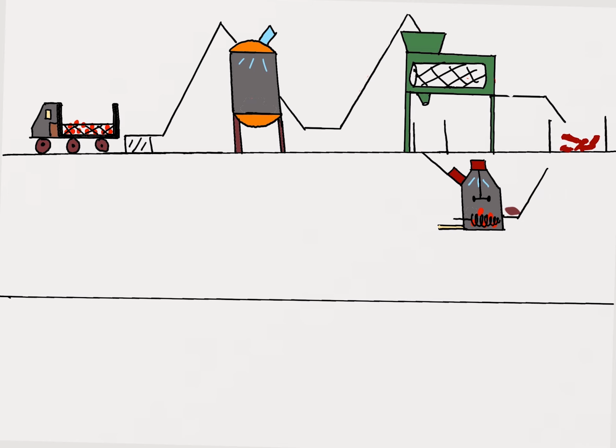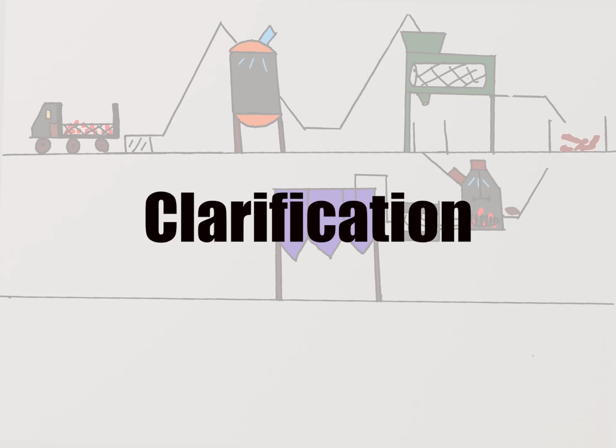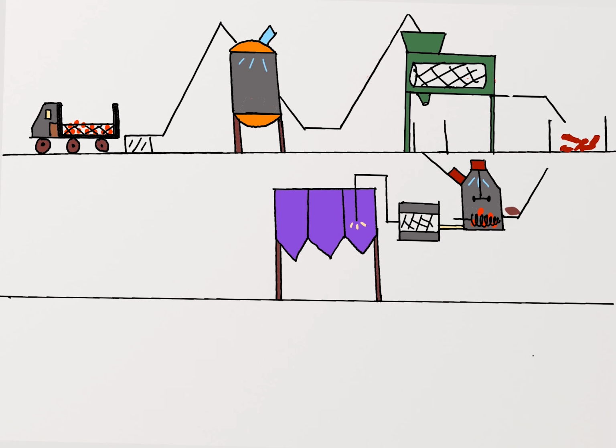The oil will enter a vibrating screen to remove the coarse solids, and the remaining oil will enter the clarification tank, which is a gravity settling tank. In the clarification tank, the oil and sludge are separated. The sludge from the clarifier has about 10% of oil remaining, which is mostly recovered by using a centrifugal separator and returned to the clarification tank for further treatment.